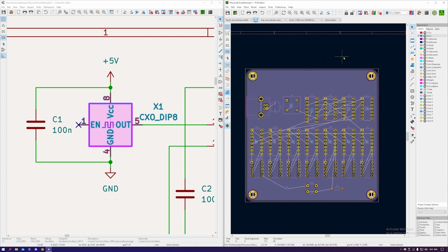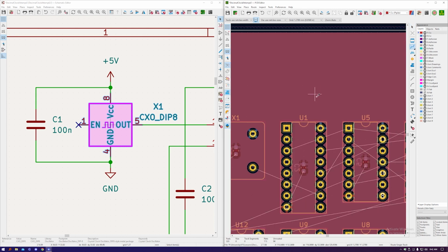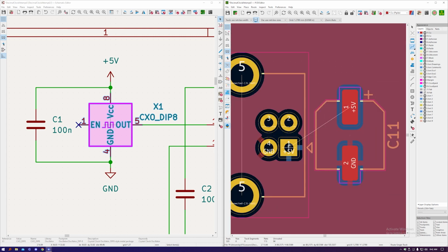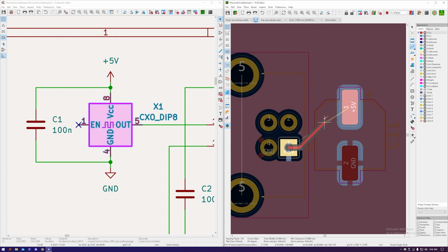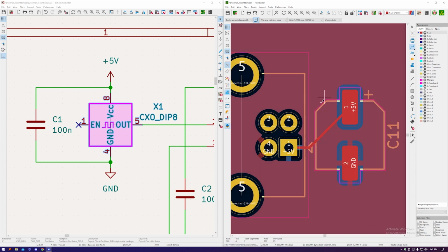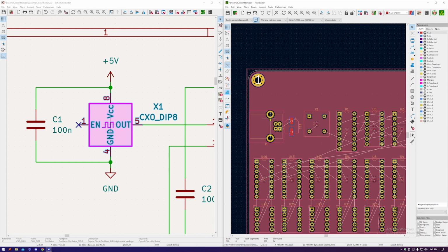And you might be thinking now, but the whole of the front is covered in copper. Where are my traces going to go? If I click on this, which is the trace tool, and let's say for now I'm just going to join these 2 pins together, so I'm going to go from here up to that. Now when I press B, it moves the ground plane out of the way for my new trace. So that's my answer to your question.